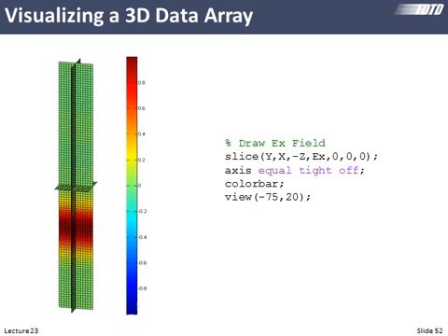So what does it look like if you do this? Here's a good example of how I do it. And this is also taking into account our rotated grid. So we give it Y, X, and Z mesh gridded. I put a negative in here, and that just flips it. There's other ways of doing that. I'm being lazy here. We can actually go into the properties of the graph and flip it or whatever. I'm visualizing the X component of the electric field, and I give it 0, 0, 0. And that's how we cut these slices through the middle of each axis.